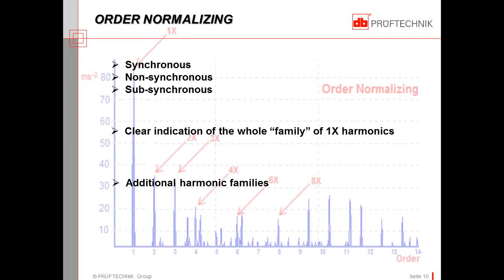And generally speaking, harmonics are never a good sign. They're never something that you are encouraged to see. Whenever we see multiple harmonics, it's usually severe misalignment, some type of looseness, severe bearing problems, and so forth. So harmonics are very seldom a good sign in the world of vibration analysis.